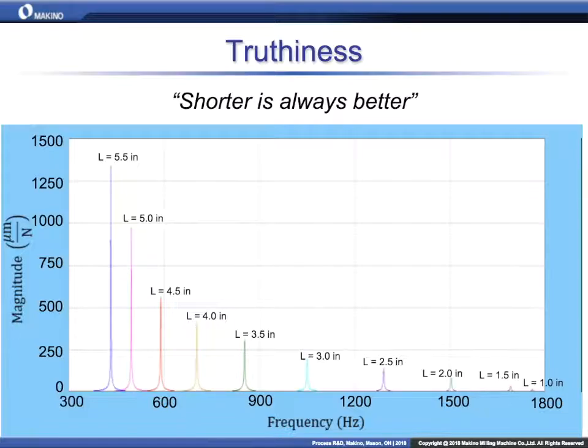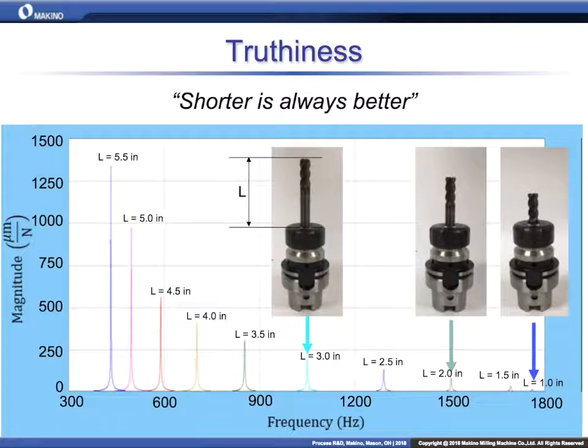So your stick out can greatly influence what spindle speed you select, as well as the stiffness of your tool, which goes right into how you best maximize material removal rate. You can't just say this tool can remove this much, because you need to know what the tool's doing, and it's strongly dependent on the stick out length of the tool.